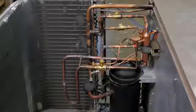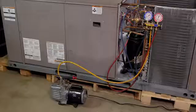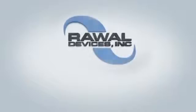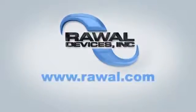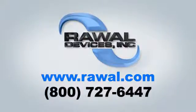Now that all the connections are made with the isolation ball valves open, evacuate and pressure check the system. Next, with the isolation ball valves closed, isolating the APR control from the circuit, you can charge the system to the factory recommended specifications. Your installation is now complete. You are ready to start your system and reap the benefits of the APR control. Do not forget to open isolation ball valves after startup.